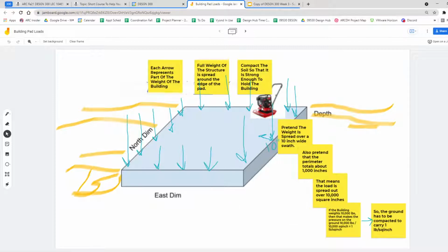Now, we also know from what we went over on Tuesday that if my bulldozer comes through and makes this pad, and my surveyor says, yep, you got it just right, and it's nice and even, and it's mixed properly, it's got all those cooking ingredients, it's got the right size gravel, the right size soil, the right amount of organic material, the right amount of colloidal material, it's been mixed properly, and I've dampened it properly, I can come in and compact it a certain percent.